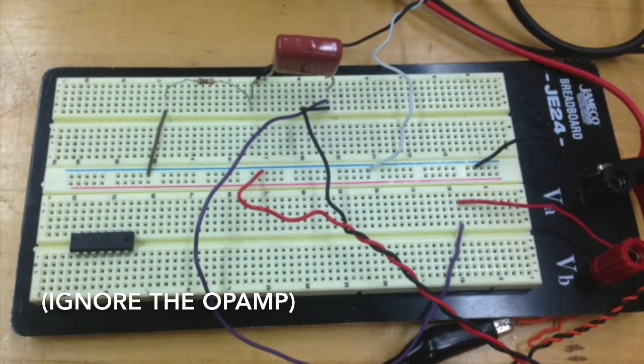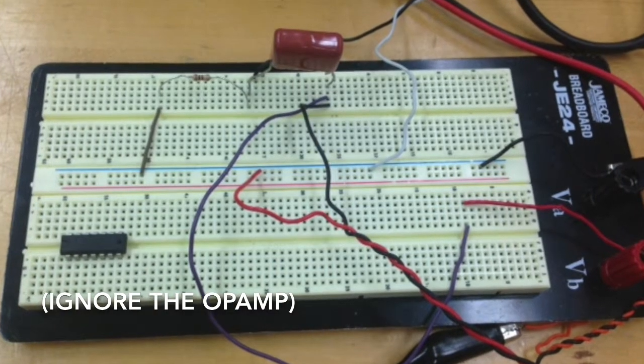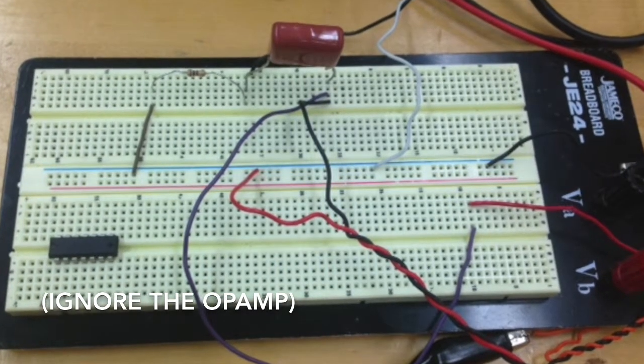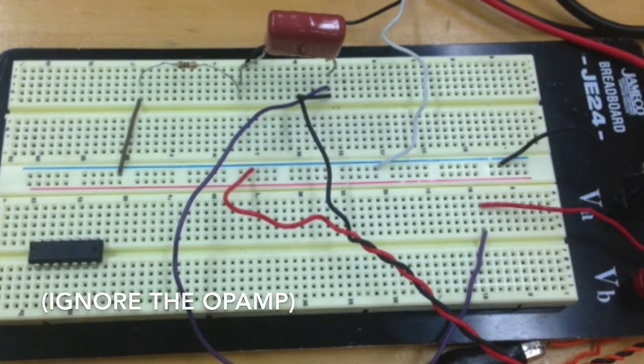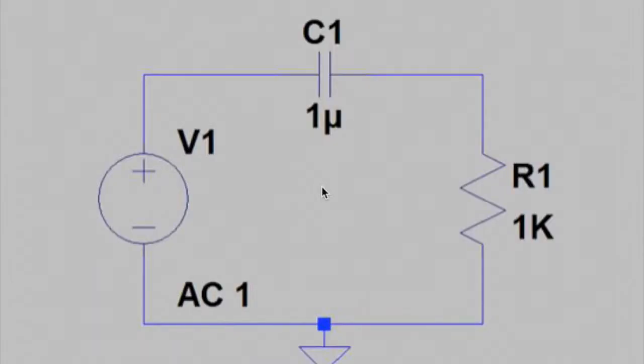Our high-pass filter circuit is the same as our low-pass filter circuit, except that the capacitor and the resistor have been switched. And here we have our high-pass circuit because the capacitor comes before the resistor after the power source, and we still have a 1 microfarad capacitor, a 1 kilo ohm resistor, and the AC sweep settings are the same as the low-pass circuit.